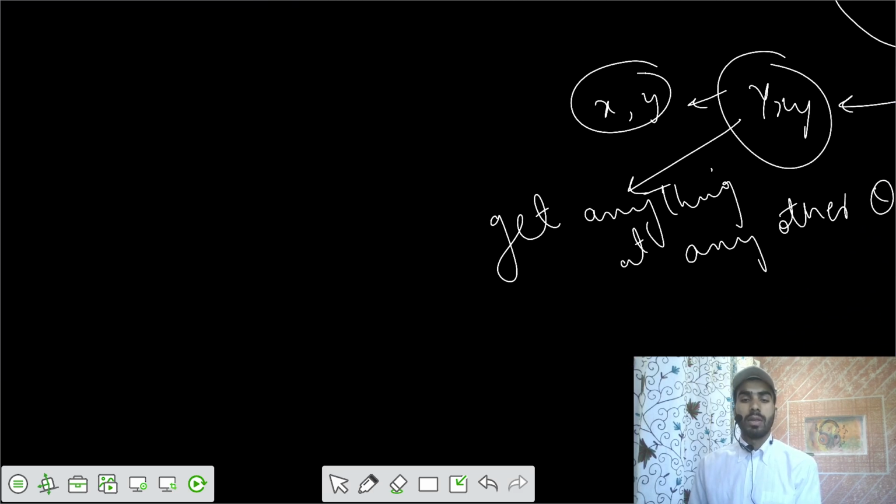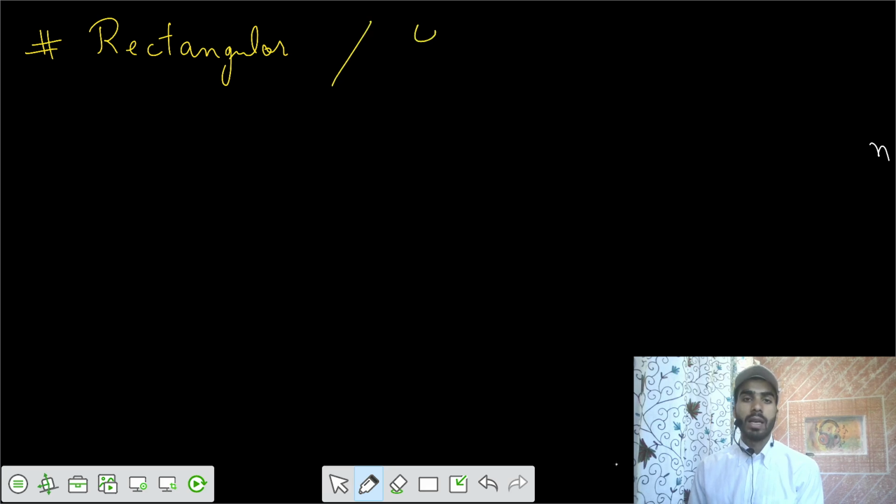Based on this, we have different types of strain rosettes. A strain rosette is a collection, an arrangement, of three strain gauges in such a way that they measure normal strains in the particular directions they are designed for. The first one is the rectangular rosette, whose special case is the 45 degrees strain gauge.